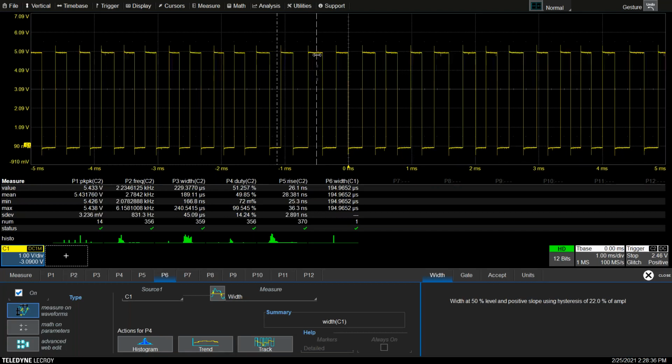So again, just to try to point out some things during this coffee break that could be useful, that are a little non-standard, that some of our customers and users forget about, is to go ahead and use the gates to define the measurement window. And they can be different for every scope, for every parameter, or you can have all the parameters be defined.